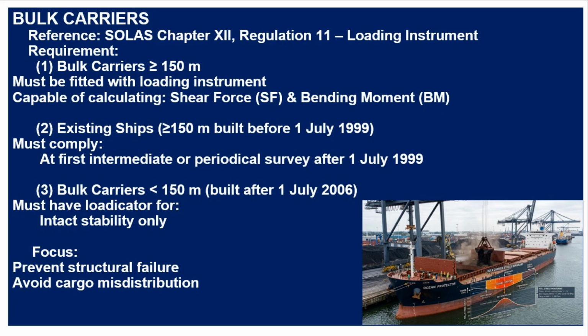3. Bulk carriers less than 150 meters, built after July 1, 2006, must have a Loadicator for intact stability only. Focus: prevent structural failure, avoid cargo misdistribution.